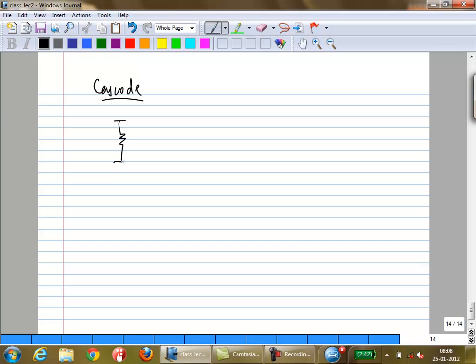Okay, so now let's look at the cascode. So first what we'll do is let's just take into account this one and this one because it's easy. The current noise flows through to the output, right? We know that. RD directly flows to the output. So let's just write the expression for M1 and RD first. Then we'll start considering M2.